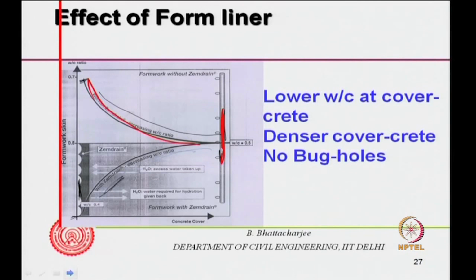and no bug holes. It gives you a fantastic finish, but unfortunately it is extremely costly and has not been popular at all because of its cost and also application difficulty, because you have to apply it over the formwork and fix it using a tape. Also, you cannot demonstrate quantitatively how much the advantage will be at the moment, other than the qualitative advantage.